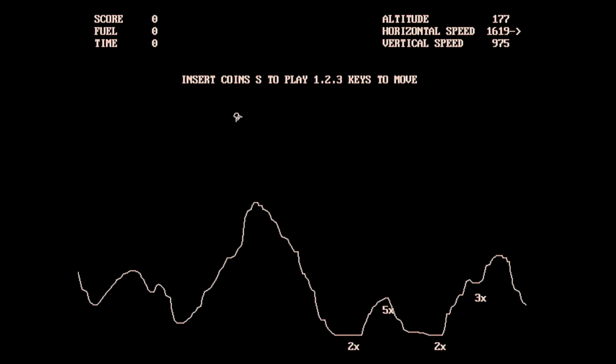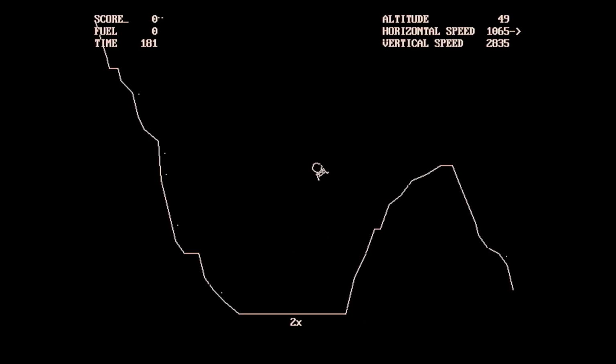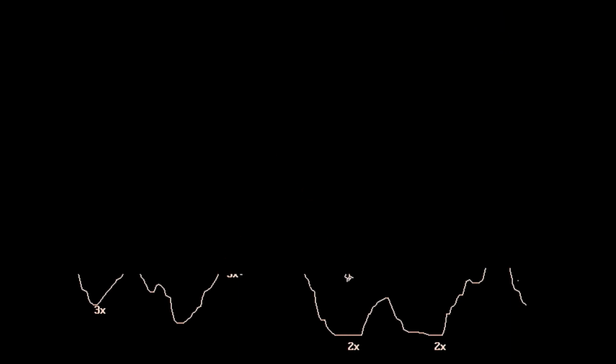And what I have realised is that it's got to the stage now where some of the more recent wiring is a little bit long and messy, and really it needs to be tidied up a little. The board needs to be tidied up a bit, and probably I should lay out the whole board from scratch and try to eliminate some of the signal paths. I did have to modify the 25 megahertz dot clock and put some buffers on it to stop some of the interference that I was seeing. So what I'm going to do is update the schematic diagram before I post it onto GitHub, and it will have some of the modifications I did to the circuit to get it working.